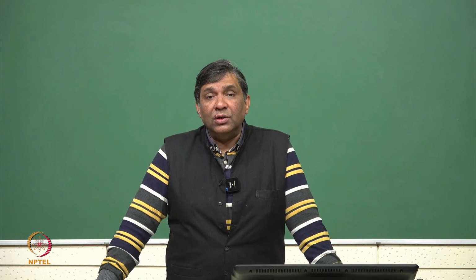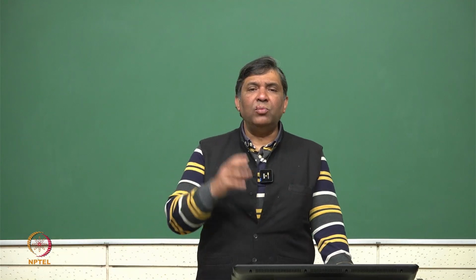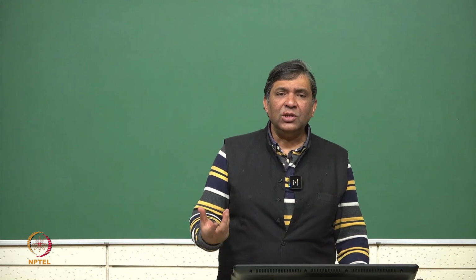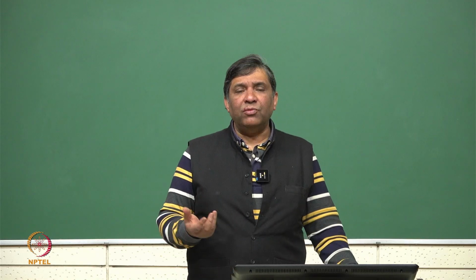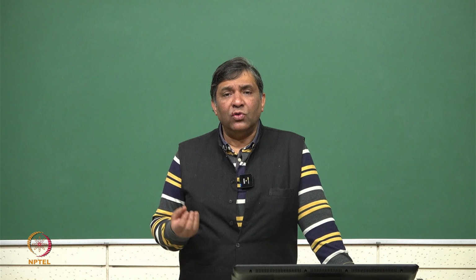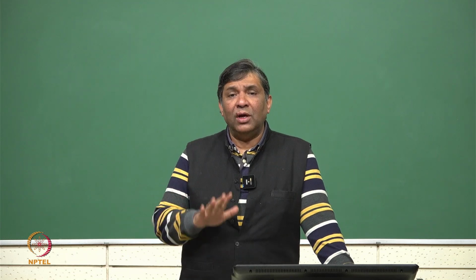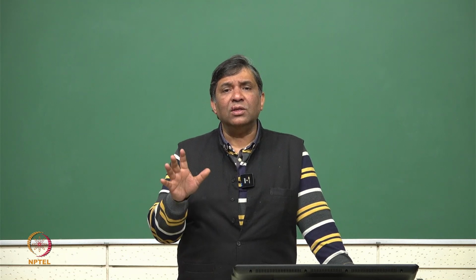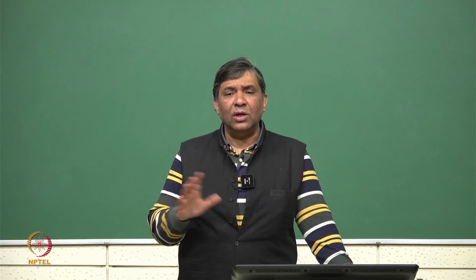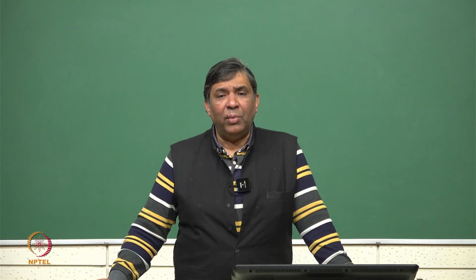Stability is a very important issue, and therefore, it is important to look at inorganic materials, and the best choice which people found after dye sensitized solar cell is inorganic quantum dots. So, one way, you can have a variable band gap. I discussed the quantum confinement effect. By quantum confinement effect, one can see how one can vary the band gap.